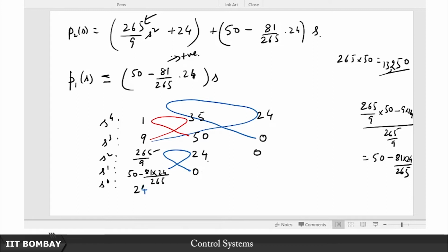So this completes the Routh tabulation, and I see that if I observe the first column, as I remarked earlier, or indeed the overall Routh array, as I also remarked in the previous lecture, if there is some defect in the system, that is, if there is some root on the right half plane, there will be some sign change in some location of the Routh array or the other.